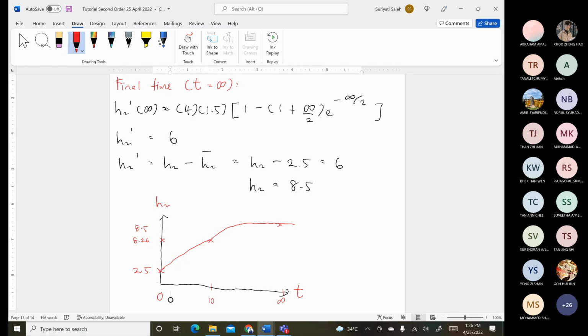So this is what we call problem solving. We start with the derivation, we obtain the single transfer functions, we multiply them to get the overall transfer function. Once we get the overall transfer function, we identify the order, first or second order. If second order, then you have additional characteristics to determine which category, where normally the second order consists of 3 categories: critically damped, over damped, and under damped.